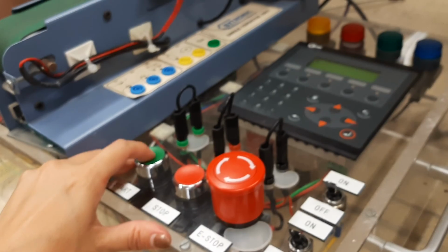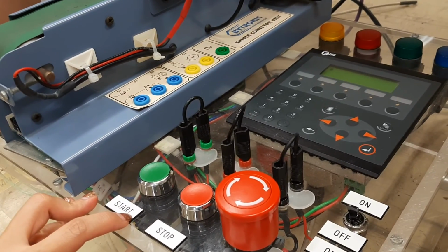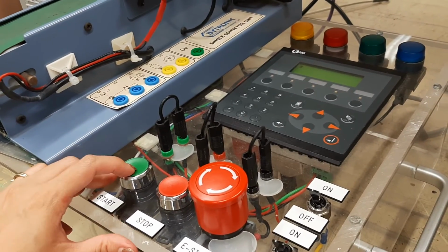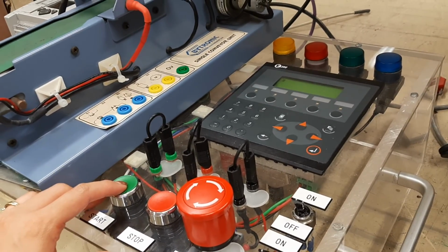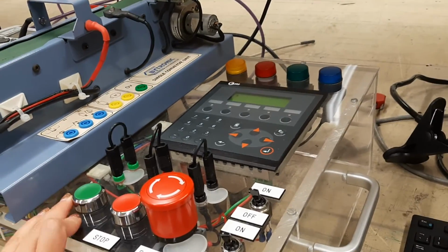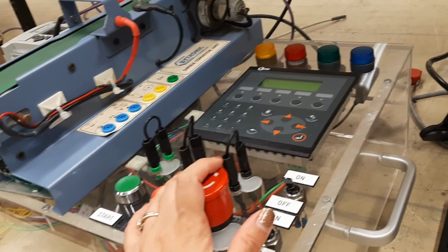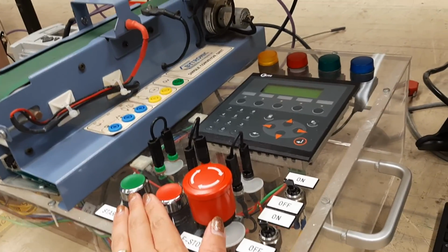Now I'm going to put the address for the input, which I want to be the green switch. It is called start. So the green button, I want the address for that. I'm going to find out what address it is, and I'm going to make a table showing what bit address is connected to what component.